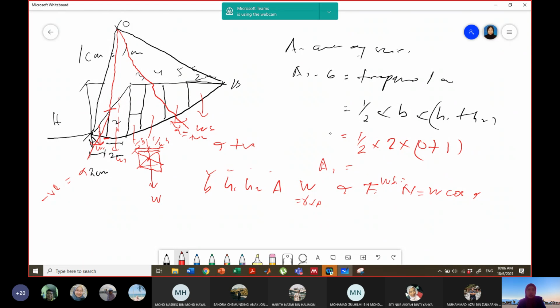After you have determined all these input parameters, please ensure you are using the appropriate formula to calculate the factor of safety. Remember, whatever method of analysis you are using, you have to check whether you are analyzing for ESA or TSA. E is the effective stress analysis, where the pore water pressure is not equal to 0, and T is the total stress analysis, where the pore water pressure is 0. You assume that there is very little drainage occurring.